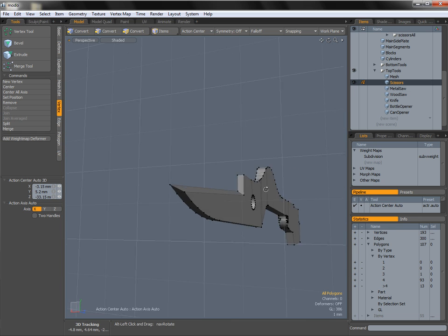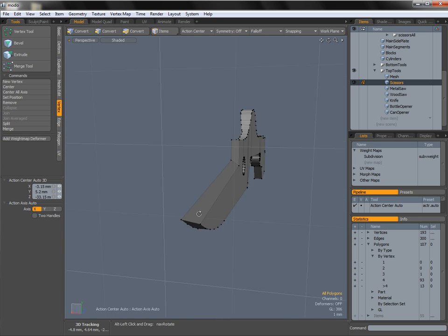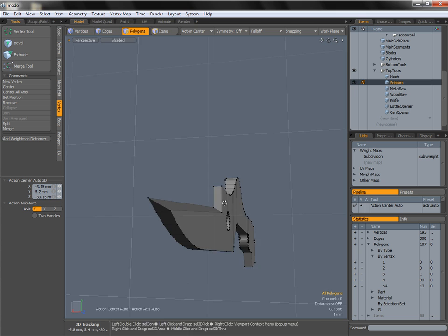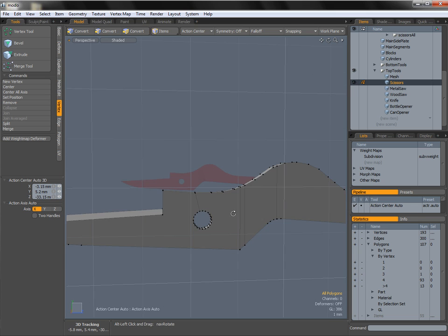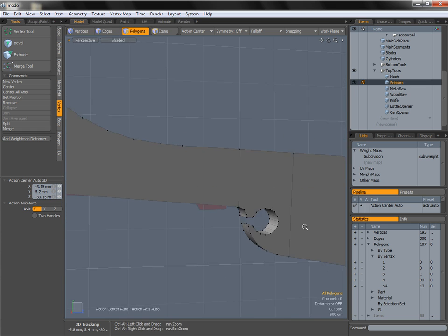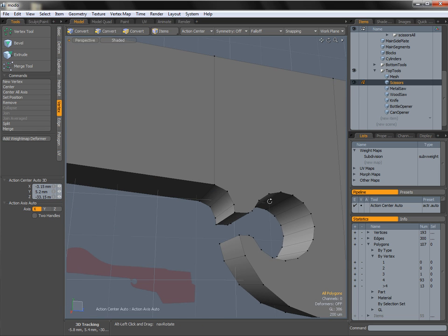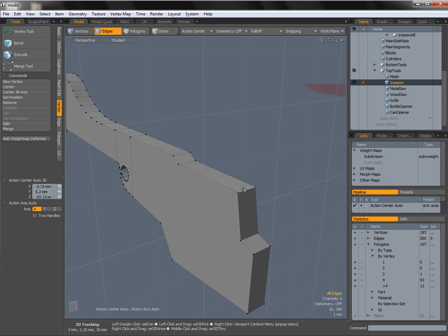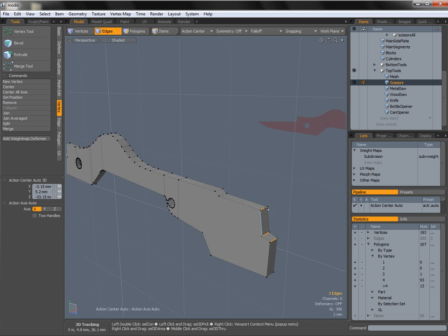We can now go around and bevel all of our edges, and then add an inset, and then we'll be adding in some quad polygons. So we're now going to go in and bevel all of the edges on the model. So it's basically all of the hard edges that make up the outsides. We're going to also go into here and bevel these ones as well. So it's basically, you know, your normal bevels really, these guys as well. And I'm going to do that and come back once it's done.